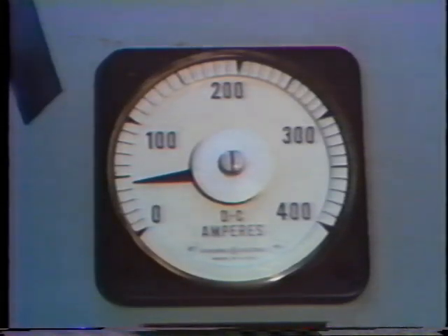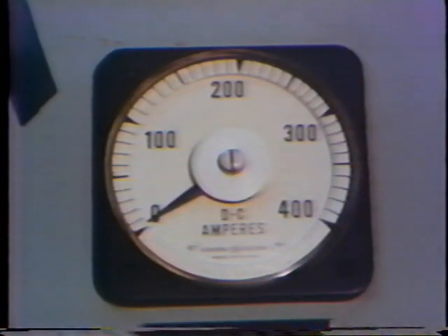The battery charger keeps the battery supplied with the amount of current it needs. For example, if the battery is completely discharged, the charger will supply it with a large amount of current. The charger provides smaller amounts of current as the battery's needs decrease. When the battery is fully charged, almost no current is needed, so if the amp reading on the meter is a high number, the battery is discharged and the charger is recharging it. The lower the amp reading, the closer the battery is to being fully charged.